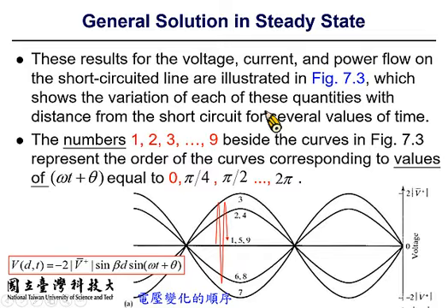And here in this plot, you see the voltage waveform of the standing wave on this short-terminated transmission line at different time instants. The numbering 1, 2, 3, 4, 5 labels the time instants of 0 degree, 45 degree, 90 degree. For any specific location, the voltage still goes up and down, which can be described as a sinusoidal function.